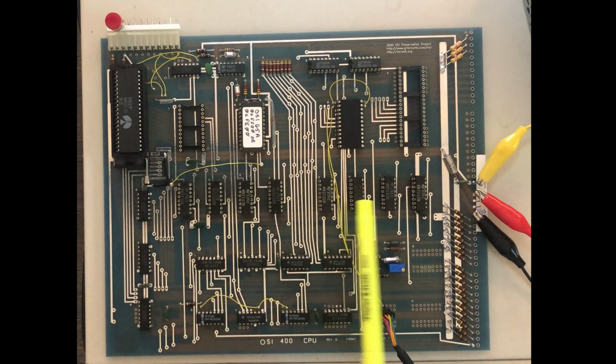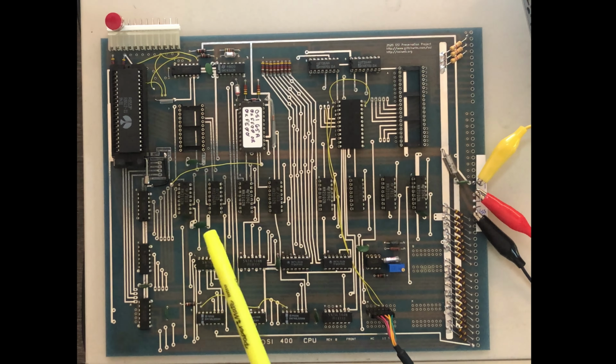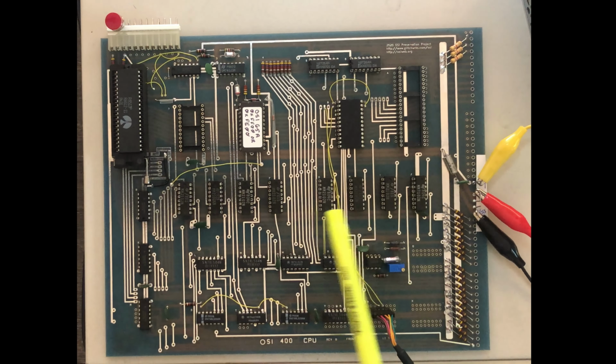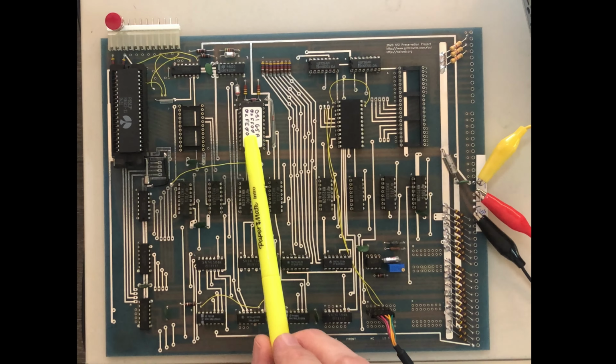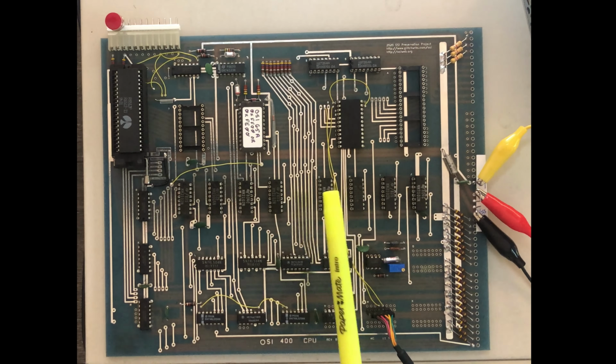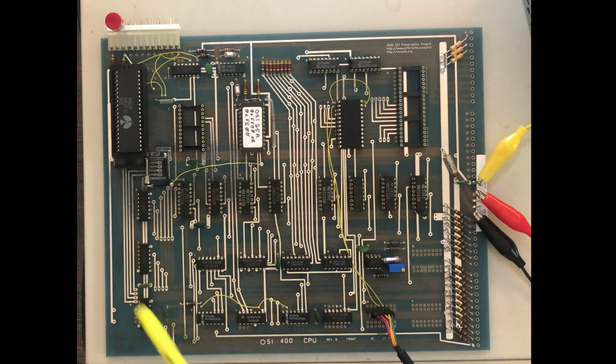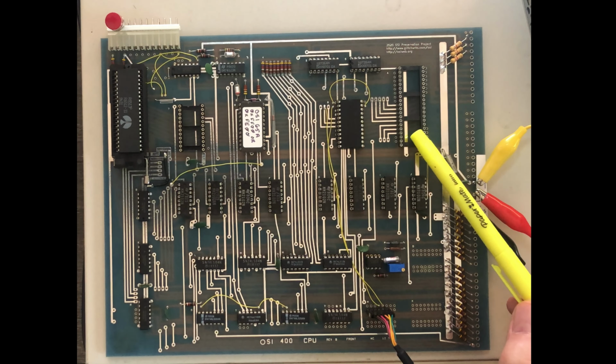There's 1K of RAM here. These are 2102s. Pages 0, 1, 2, and 3 live down here in these. This ROM's mapped up in the higher address space so that the reset vector up at the top of memory is there, and then the ROM runs up in that higher address space. There's some glue logic on here for making things work. There's an unused socket here that all kinds of different MOS chips could go into, depending on what you wanted to do with the board.